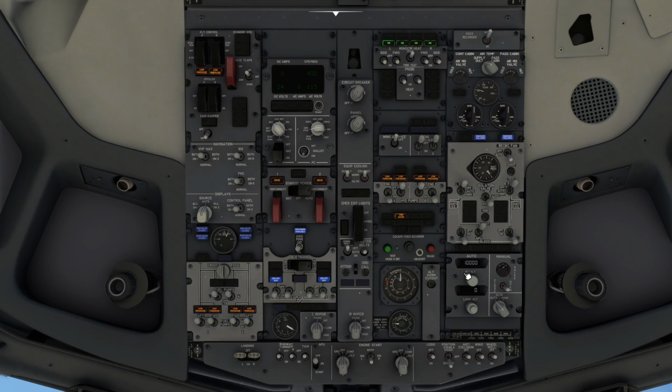We can preset the cabin air pressure to our cruise altitude, so the environmental control system I should say. So we tell it we're going to be flying at 36,000 feet and it does everything it needs to in terms of pressurising and heating the cabin appropriately. We turn aft fuel pump number 1 to on. And then we turn on the auxiliary power unit.